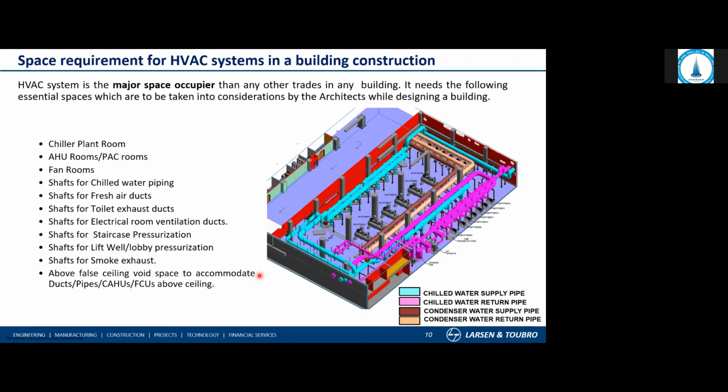So it is very important to assess the space required between the false ceiling and the true ceiling. One major part involved is the structural element, which is beams. So we have to see how we can accommodate our system in discussion with structural designers and other MEP services, because the void space is the only space where all the services run, including HVAC ducts, piping, electrical trays, fire pipes, water supply pipes, LV trays, fire protection, fire detectors, everything on top of that.